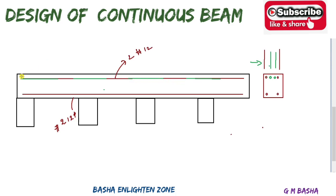And you can keep one full length bar from here to here, like two full length bars from here to here. So these two bars you can keep full length also, no problem. But at the supports, minimum 4 bars will be required. But if you keep an extra bar here also, no problem. But for satisfying that condition, minimum 4 bars at the support will be required. Coming to the downside, at the middle span, minimum 3 bars will be required.